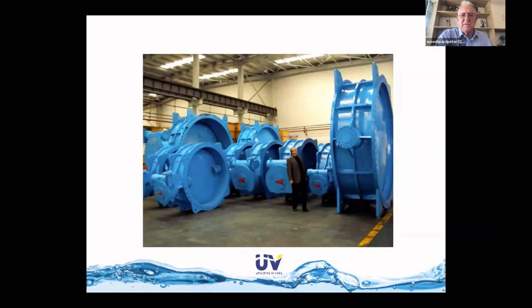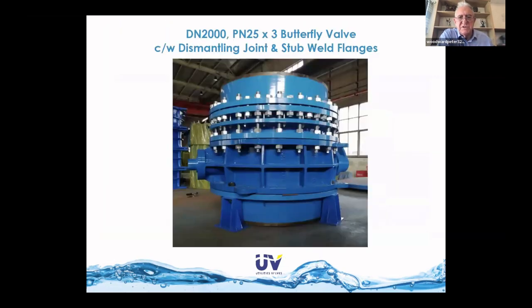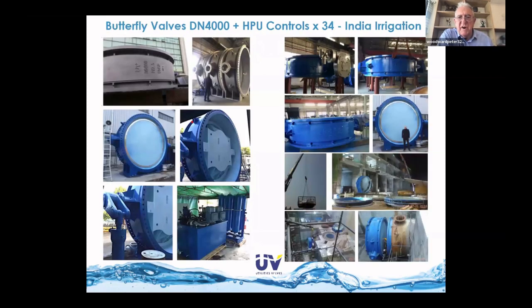Large diameter butterfly valves is where we have also developed special sealing. And as we go forward with the slides, here we see this is a 25 bar valve. Here's a project which was 34 valves, 4 meters diameter, complete with the hydraulic power pack unit controls for a large irrigation project in India.